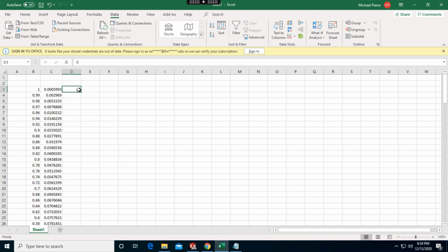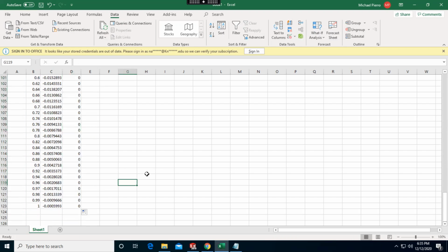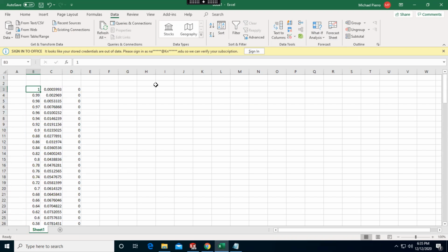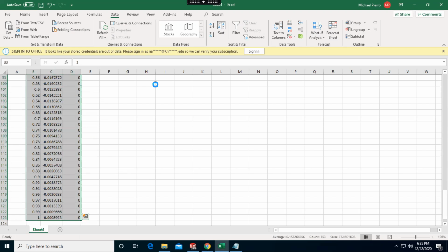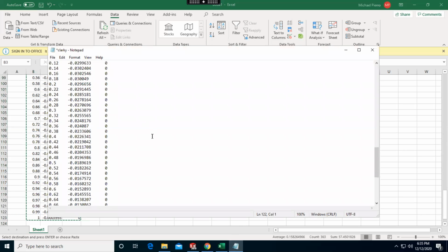So we add all these for our 2D airfoil, just like that. And now all of our coordinates are set and ready for SolidWorks. So we will copy all of them and replace them in this text file. Just have to make sure that the zeros right here are in line with all the others, just like that. And save.